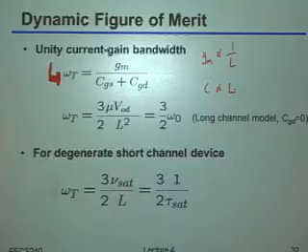Okay, so now just to be totally clear, if we were to take an extremely short channel device, and by this I mean something that's completely velocity saturated, I've already shown you here that I now claim that the omega t would only go linearly with the channel length. So why is that? Out of the two terms that we said above were both changing with length, which one of them is no longer changing with length, when you have a completely velocity saturated device?